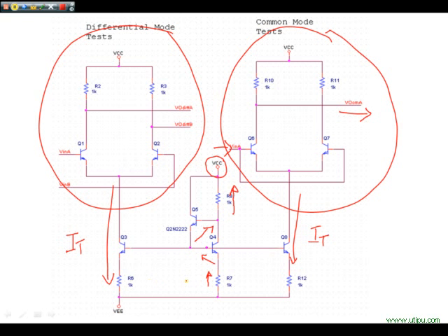I'm not going to tell you how to design that. You should know how to design that, and you should know all the equations. If you're designing to the previous specification, this value, the tail current, is 2 milliamps. In the laboratory spec, I've said I want 2 milliamps for both circuits, and I've suggested that the reference line should be 1 milliamp, approximately. Remember, we're going to make this an approximation.